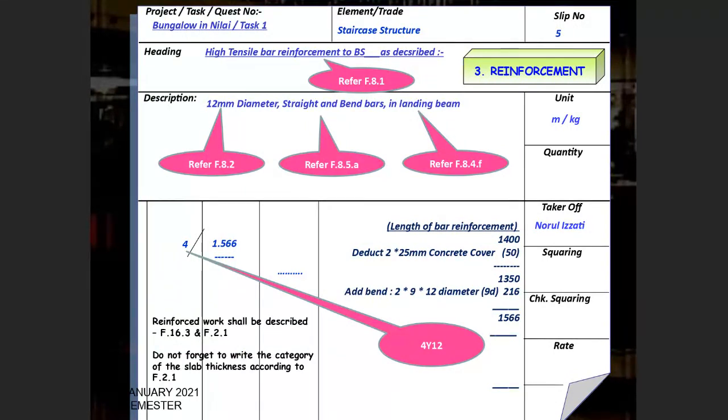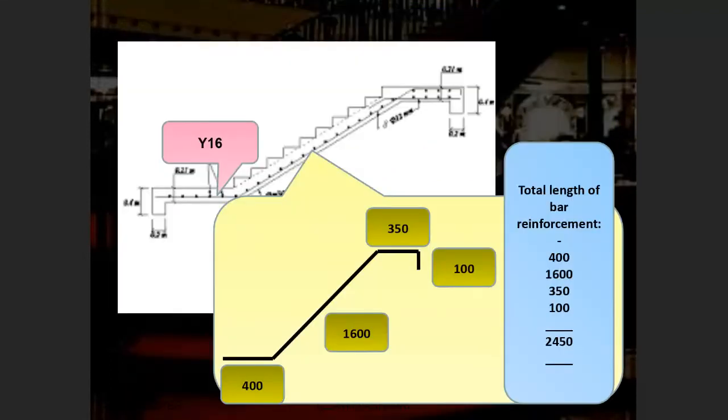I would like to see all the students show this. Show one by one how you deduct the concrete cover, how many bends you have to add in, any formula, and you have to multiply by the number of bars. This is one of the examples.